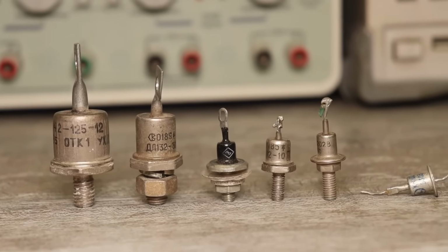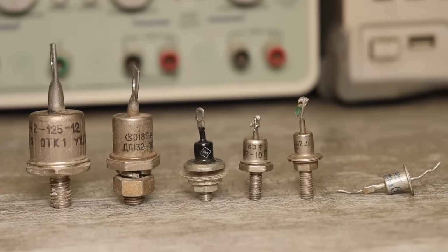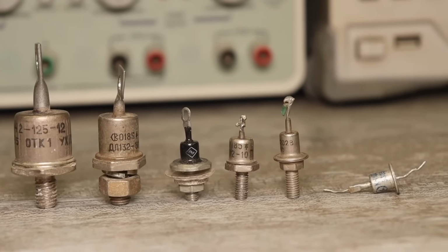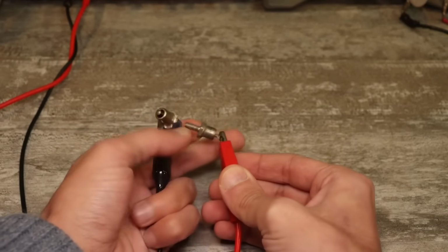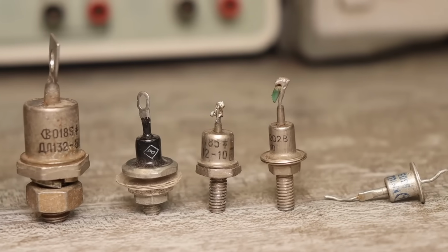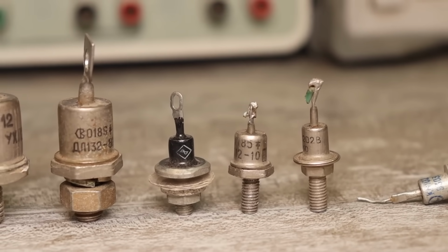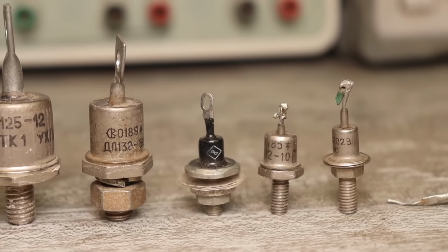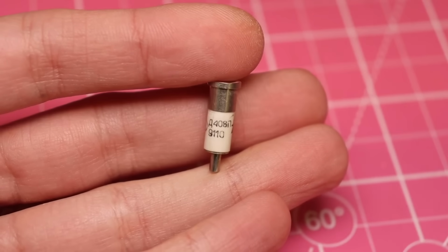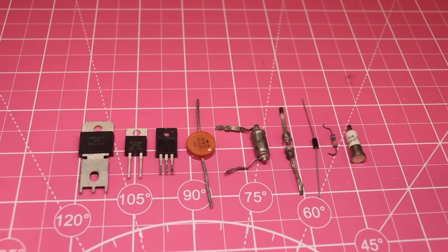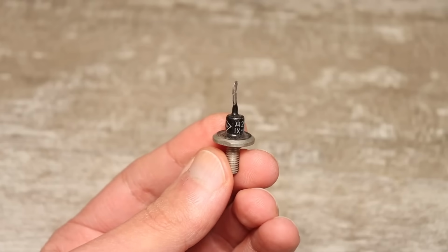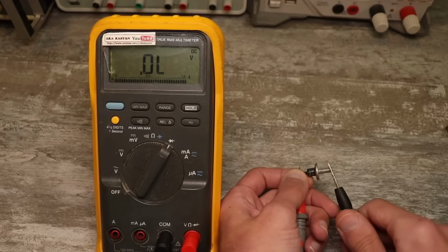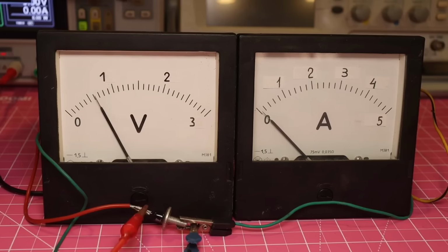The semiconductor diode. You'd think, what could be simpler? The good old diode with a single PN junction, which conducts current well in the forward direction and hardly at all in the reverse. Of course, diodes come in all sorts of varieties. Low frequency, high frequency, and even ultra-high frequency diodes. They differ in current, voltage, reverse recovery time, and so on. For a classic silicon diode, the forward voltage drop is about 0.6 to 0.7 volts, and it increases as the current flowing through it rises.